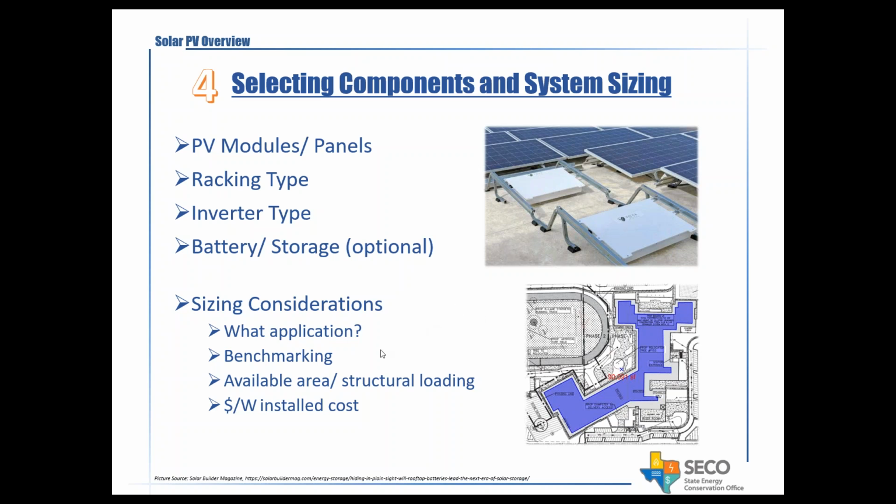Other considerations is you may want to do some benchmarking of your building before, or to help you decide how big should the system be. You'll want to know what's your annual kWh or electric consumption. You'll also want to know what's your peak kW profile look like, and that can help you in deciding how big your system should be.